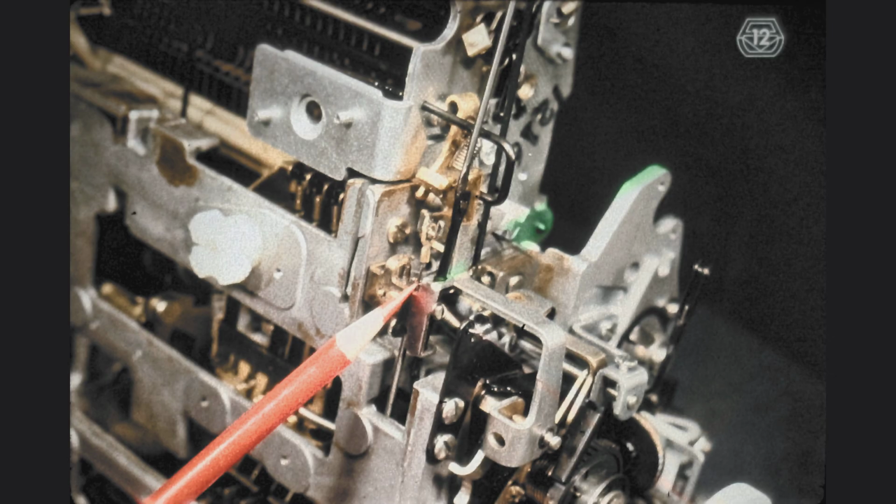If we now take another look at the position of the roller on the print cam follower, we find that it has indeed been shifted toward the left, hopefully far enough from the front lobe of the print cam. But what if we wanted to know exactly where our cam follower rides on the print cam during a routine print operation?